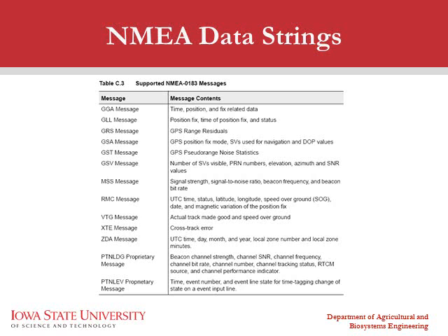For example, a very common indicator is the GGA message, which includes core information like time, position, and GPS fix related data. There are other messages that are used, including messages that tell us how many satellites are being accessed, the speed at which we're traveling, PDOP levels, and other quality indicators for GPS.